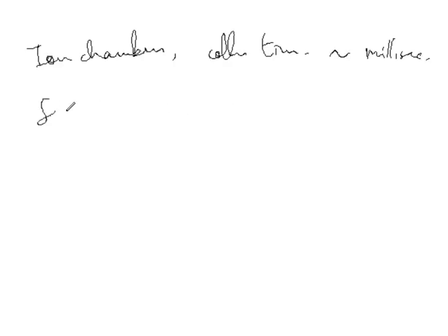Whereas in semiconductor detectors, do you know how much the same collection time is? You will be amazed to know it is of the order of nanoseconds. These times reflect both the mobility of the charge carriers within the detector active volume and the average distance that must be traveled before arrival at the collection electrodes.